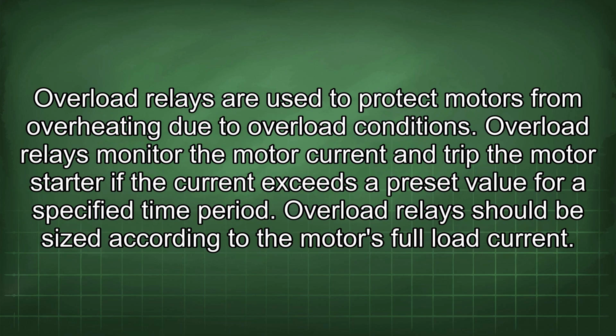Overload relays are used to protect motors from overheating due to overload conditions. Overload relays monitor the motor current and trip the motor starter if the current exceeds a preset value for a specified time period. Overload relays should be sized according to the motor's full load current.